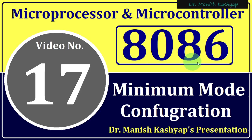So multiprocessor mode is also useful, and it is not necessary that there are only 8086 microprocessors in multiple numbers in multiprocessor mode operations. There could be different kinds of processors. Some of them may be dedicated to some purpose, like 8087, which is dedicated to your mathematical operations. There could be some microprocessors dealing with other tasks and so on and so forth. So that's why multiprocessor mode is also useful.